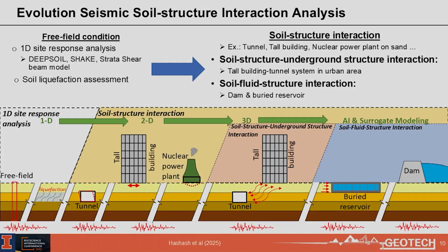I'm now shifting from static to seismic. When we're dealing with seismic soil structure interaction analysis, we often start with a free field evaluation, and with that, we start with 1D site response. Some of the work we've done at Illinois that resulted in the development of DEEPSOIL is an example of that. Earlier versions would be SHAKE, STRATA, and shear beam models. We also do liquefaction assessment.